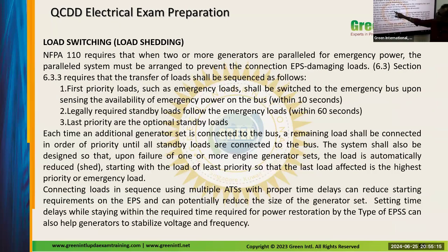First priority load, we have 10 seconds. Legally required loads, we have within 60 seconds. All other loads depend upon the requirement. We just need to remember these 2 words. First priority load we call as high critical loads.